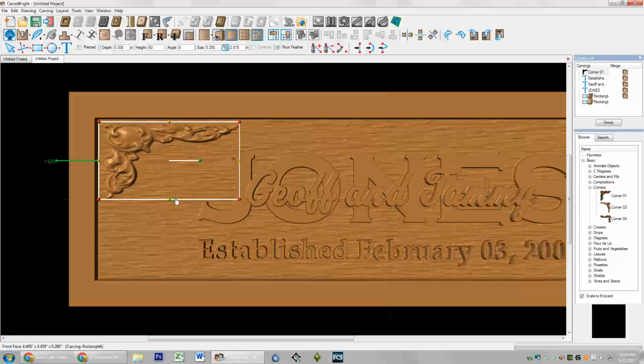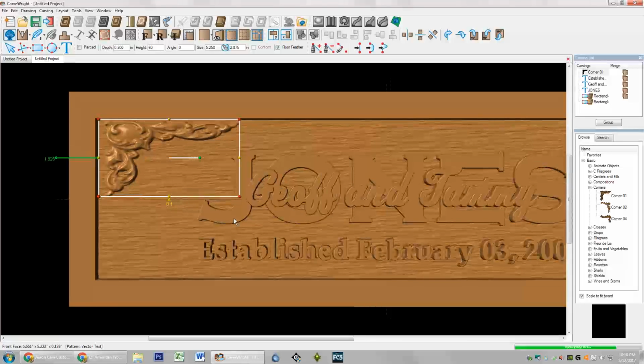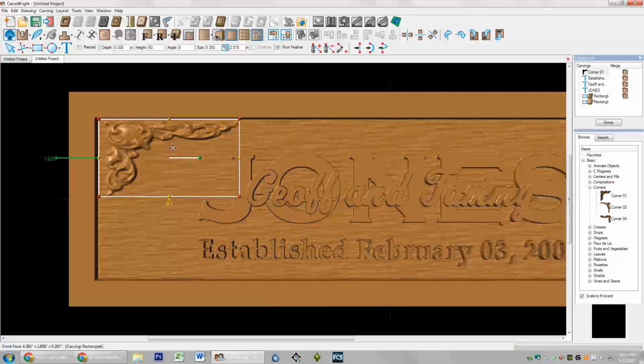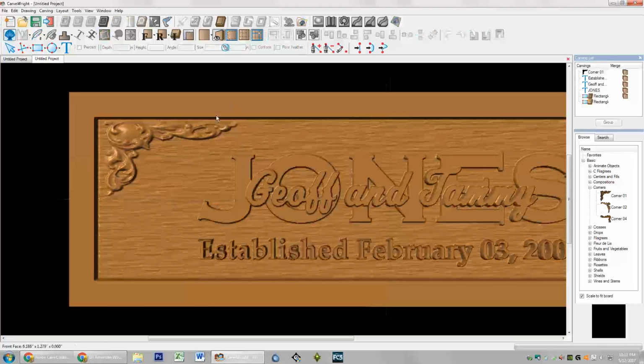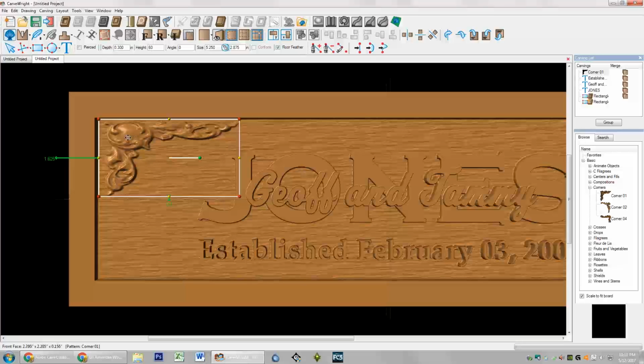If, say, I put that at 0 and then I just decided I changed my mind and I want to come in and put it at 0.1, if I did that without removing it first, instead of moving it, it would actually shrink the height by 0.1. So that's one issue I have with attachments. Another issue I have with attachments is if I'm doing mirroring or if I adjust other elements, attachments can cause problems. So I will use attachments to move things, but then I immediately remove them. That's just my own personal foible, again, kind of like the grid.